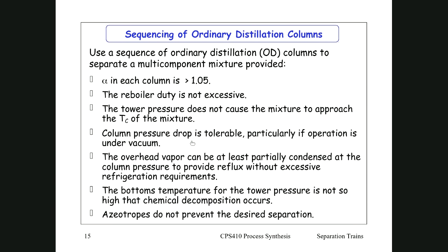So as soon as you have 10 of these, you have 1 meter of water head from the bottom of the column to the top of the column. And with atmospheric distillation, that's fine. 10 kPa in 100 kPa is not a problem. But as soon as you have a vacuum distillation, something working at 0.1 kPa absolute, then there's a big difference in the absolute pressure at the bottom of the column compared to at the top of the column.